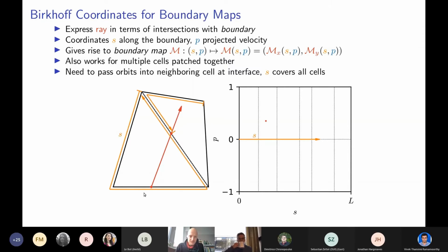So we first count the first triangle in total. These are these three patches here on this S-axis. So these dotted lines correspond to the vertices of the mesh. And then we take again another arbitrary origin, so for example here, and start counting in the second triangle from here on, so that we can attribute this value of S. So this plus this plus this plus this and then plus this to be the new value of S for the next iteration.